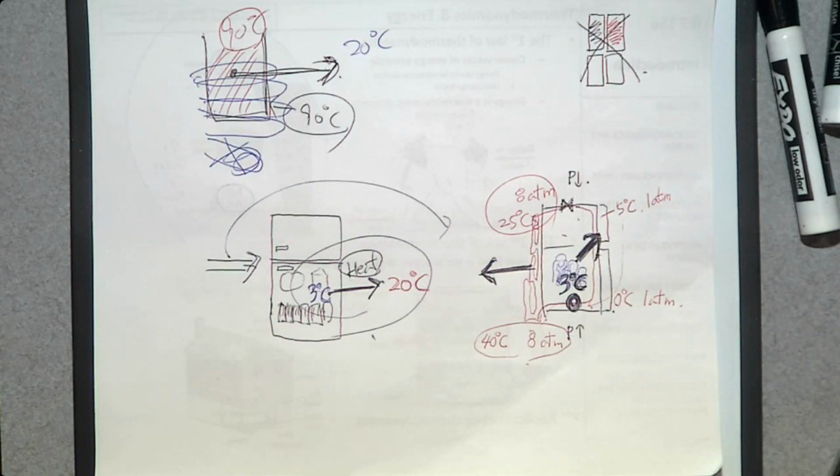And I forgot to grab this one after this class. And then tomorrow, I see the cup again. What is the temperature inside the coffee? Room temperature, 20 degrees Celsius. That's the lowest possible temperature it can go down to. Because if it goes lower, that means there's a heat transfer from the air to the coffee. So eventually the final temperature is going to be at thermal equilibrium, which means that the temperature of the coffee is the same as the temperature of the air. So the lowest possible temperature is going to be 20.